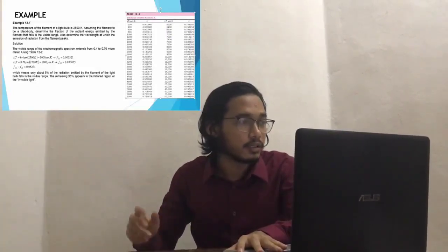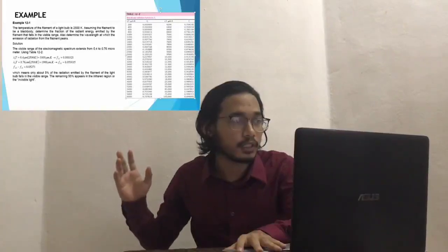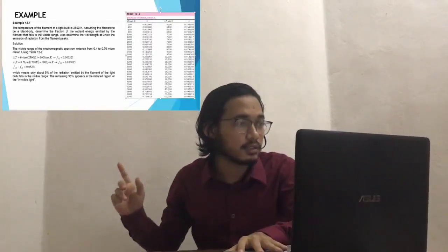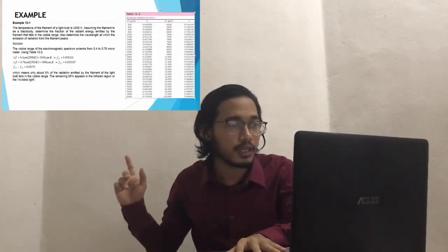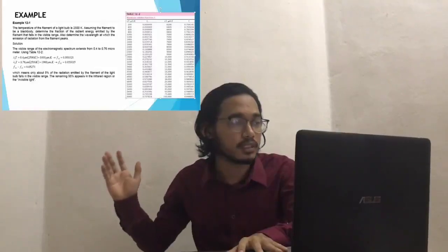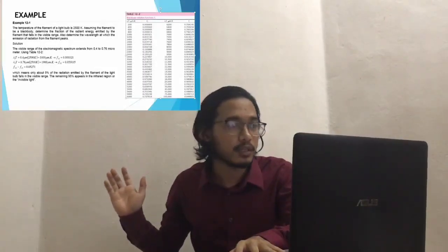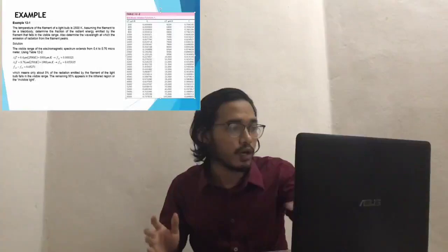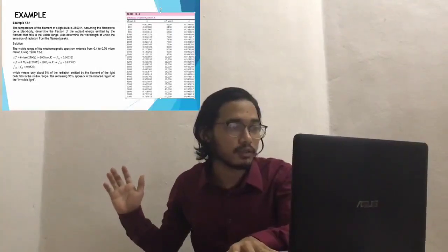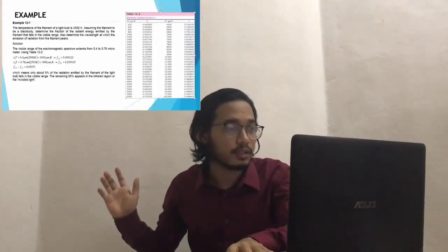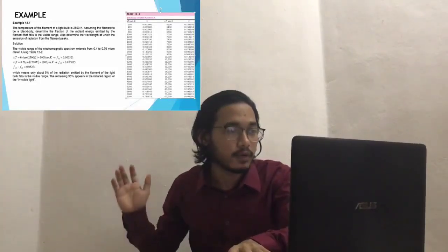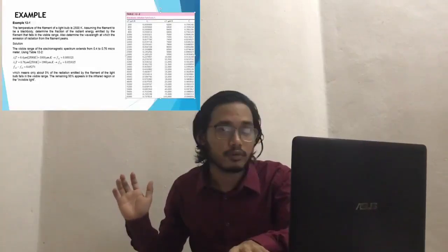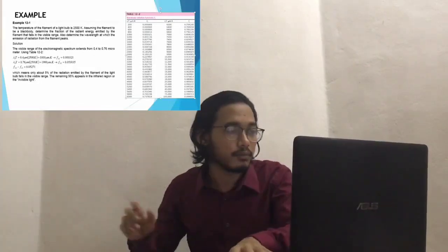We can see the temperature of a light bulb filament, 2500 K, is set as a filament for the visible range. The visible spectrum extends from 0.4 until 0.76. So by using the proper formulas, we get 1000 μm·K and 1900 μm·K. By referring to the tables, we can identify F1 and F2, and we apply the formula as in the figure and get 0.05271.